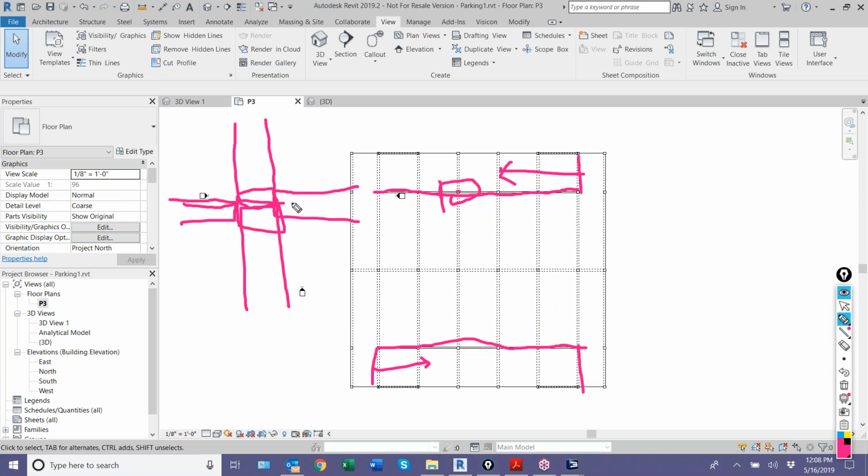Otherwise, if you have the opening floating through the column, there's a possibility that the nodes of the beams and the column actually shift to one side or the other, and the opposite side that's shifted from is disconnected. That would become evident after you run the analysis and you see large displacements in that region where this joint wouldn't be connected.